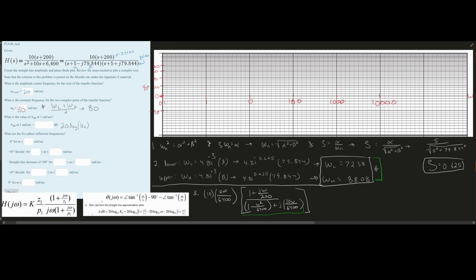So we're going to go until we hit 72.38. And this is going to look like the last factor on page 96 of our notes linked below the like button for the phase transformation. We can see it's similar because they both have the j, and this is for imaginary numbers. And since it's in the denominator where the poles are, it's going to be going downwards. So we can start by graphing this. We know that the omega L, so the lowest part, is going to be at 72.38. Just for clarity, we can write this right here. I know it's more like 50, but since 72.38, and the next part, which is 88.08, are so close, we need to be able to see them.